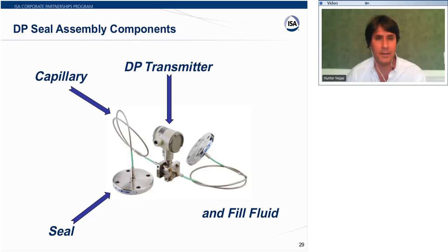The fill fluid is filling the whole system. When the vendor puts together this package, you have to special order it. You have to order all the different parts, and then he'll put it together and send it to you. And he evacuates all of the vapor out of this system. If there's any vapor inside of it whatsoever, it will not function very well, or it may not even function at all. So he evacuates all the vapor out and completely fills it with the fill fluid.